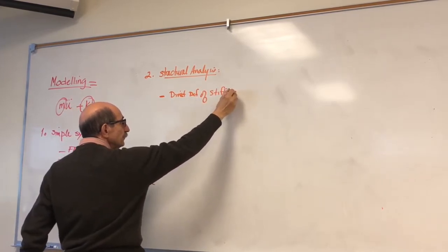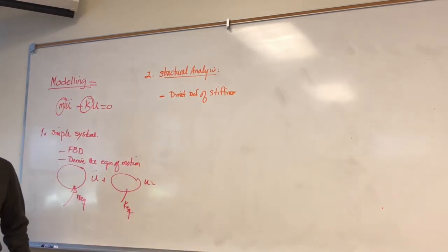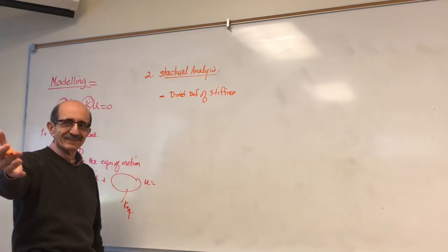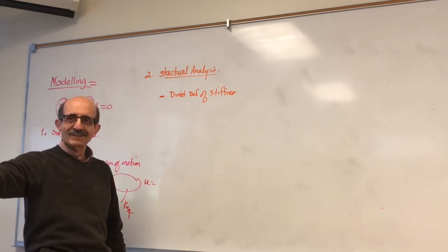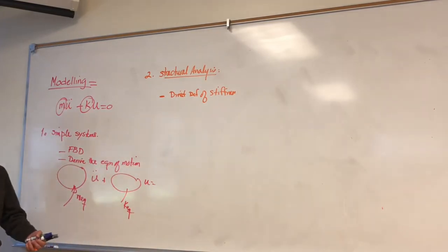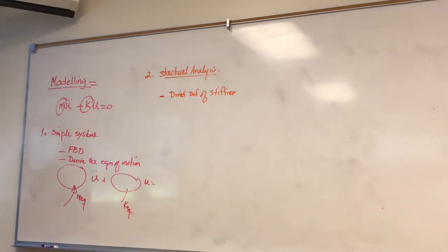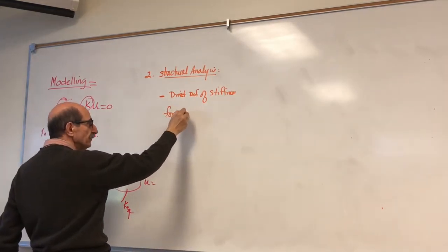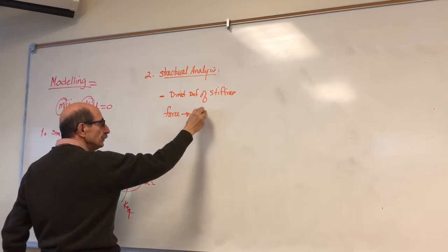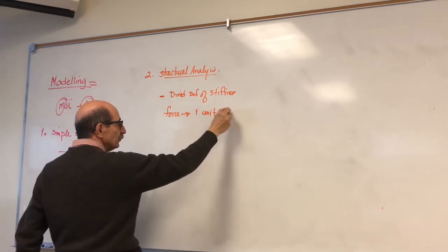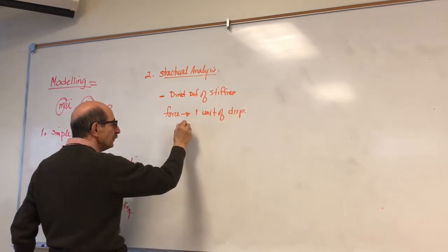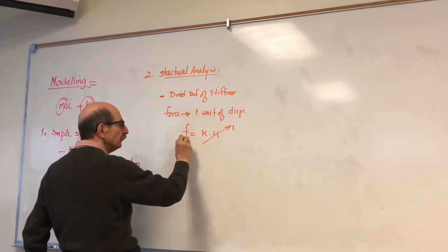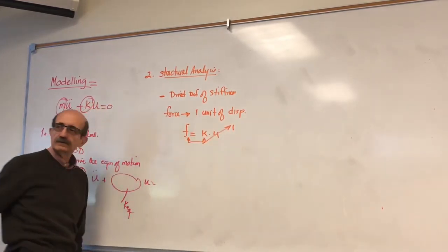What is the stiffness? What is the stiffness? You should know. Okay. Yes. What is the stiffness? It's K, but what is it? The amount of force required to move it 1 unit. Yes, so the force that generates 1 unit of displacement, right? Always remember this, F is equal to K U. If U is 1, then the force is that stiffness.